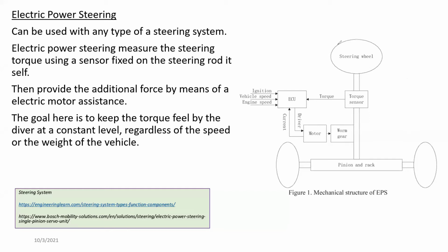So you have the steering wheel, right? You actually have your connection with the vehicle through the steering wheel. Then the steering wheel has a direct steering shaft that comes to the rack and pinion steering. So you have the rack and pinion. So you still have the direct connection, a direct physical connection. In the steering shaft, there's a small sensor. We call it a torque sensor.